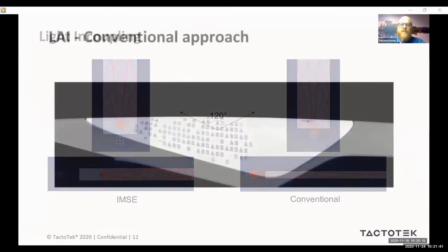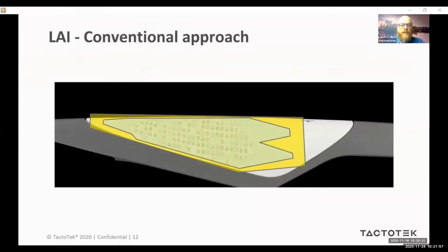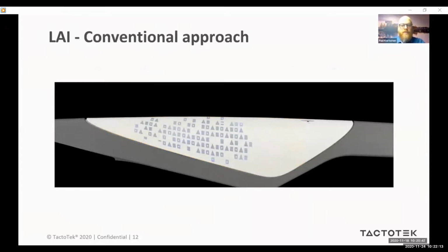Let's take the door trim as a design example where we can compare these technologies. In order to build illumination for such surface with conventional methods, we need a frame which is used as a base part of the illumination assembly. The frame holds the light guide that is used to create uniform illumination to the trim surface. The frame also reserves space for LEDs and PCBs which are located close to the light guide. The topmost part is the visual part with decorative surface.